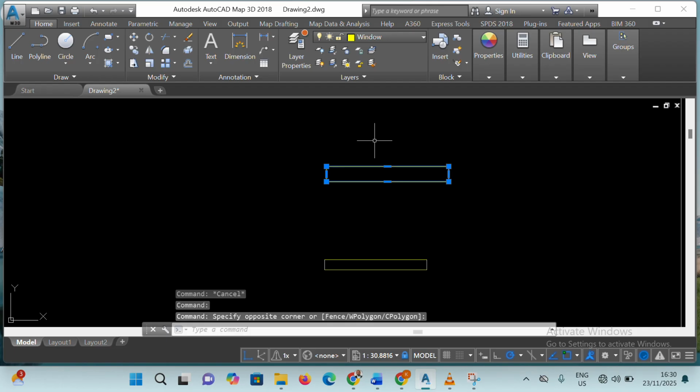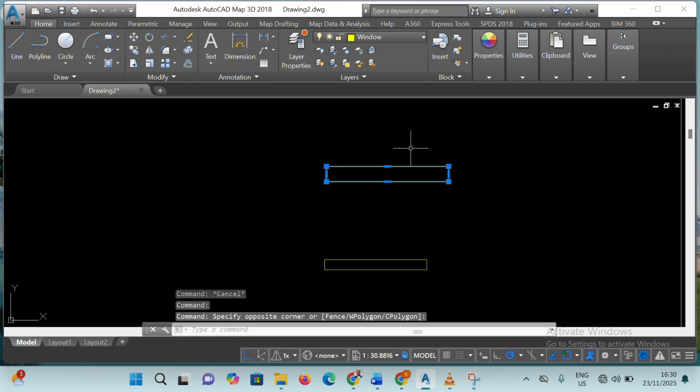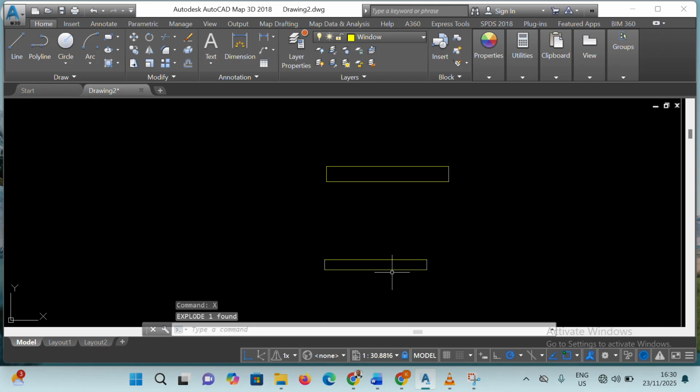So we are going to make some offsets of some lines at 1 inch intervals, and this is a complete block. So we are going to explode this into lines. We change this into lines by just pressing Command X, and then we press enter, and this will change to lines. The same thing with this one: Command X, enter, and it changes to lines, so that when we want to offset, we offset them by line.